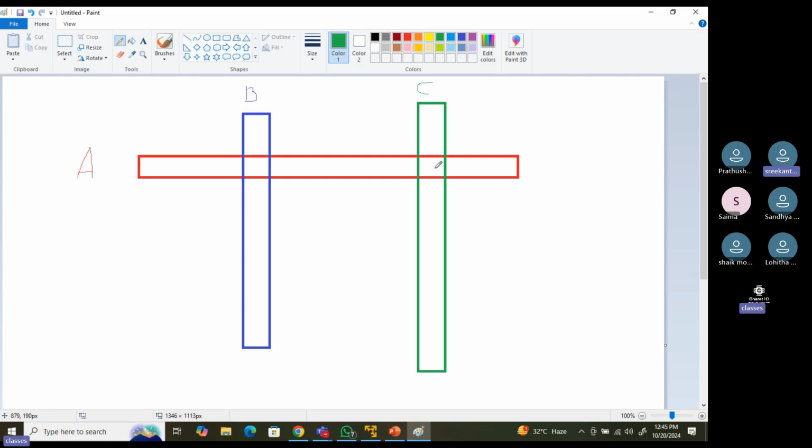You can route different nets, but a different metal should be there, not the same metal. If you use the same metal, you have to maintain the spacing between them. It cannot overlap each other. If the same metal of a different signal overlaps, it will get shorted.